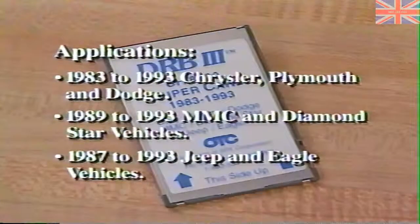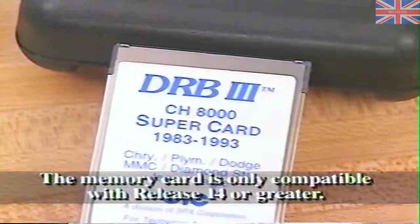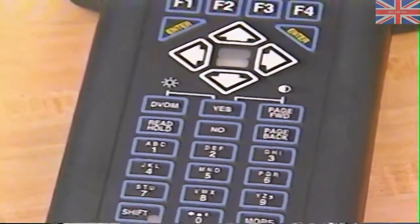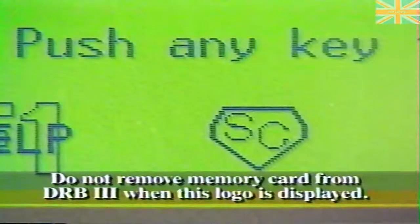1983 to 1993 Chrysler, Plymouth, Dodge, and MMC and Diamond Star vehicles, and 1987 to 1993 Jeep and Eagle vehicles. The memory card is only compatible with standalone DRB3 software release 14 or greater. Be sure your DRB3 is updated before trying to run the memory card program. And when using the memory card, be sure never to remove it from the DRB3 when the SuperCard logo is displayed. Now you should be all set to run diagnostics for most any vehicle that comes your way.